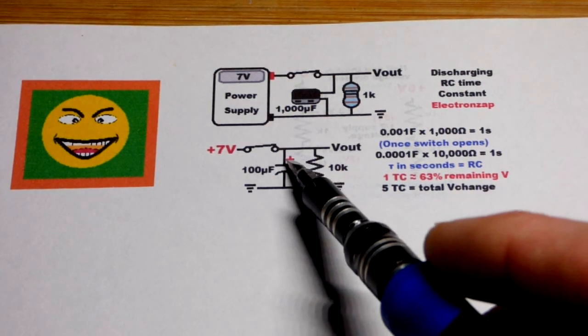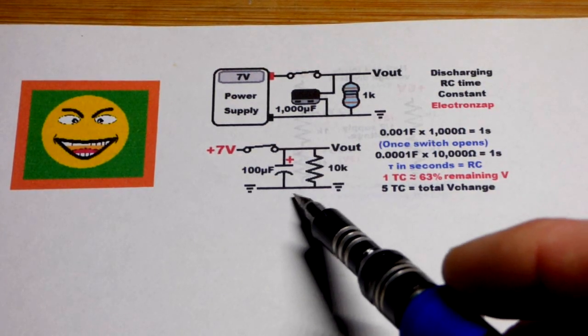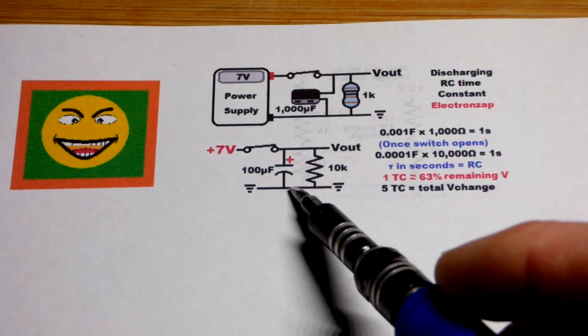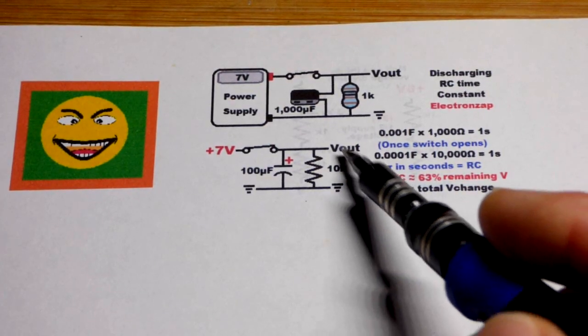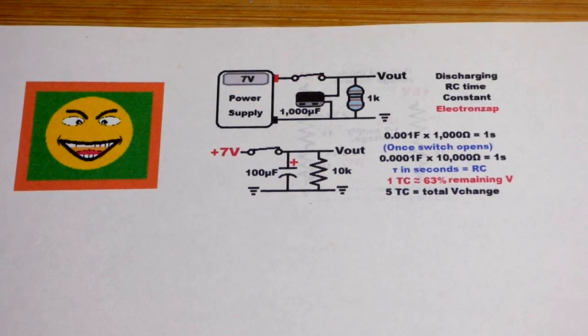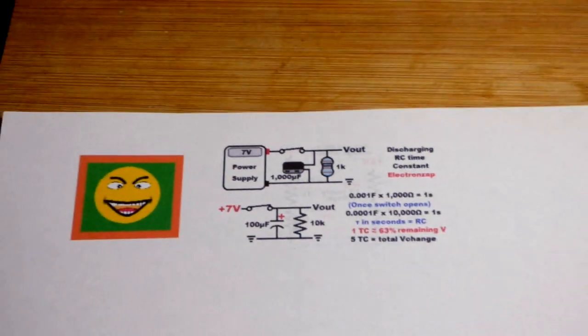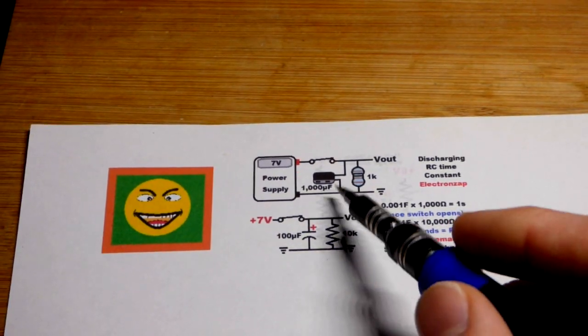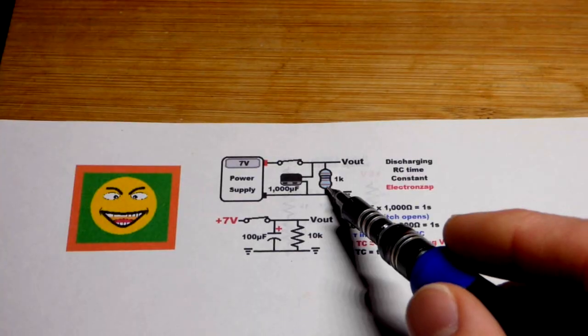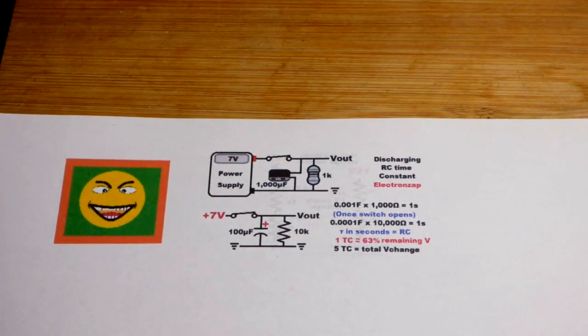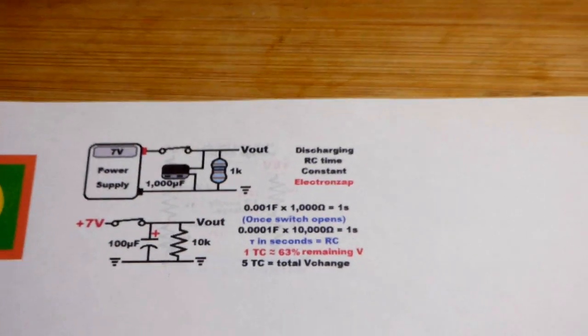You can charge the capacitor and then have it discharge through the resistor when you stop charging it, and you can take the time to do stuff. You can look at the voltage and whatnot. We'll zoom back and look at another version. 10 times the capacitance, 1/10 the resistance, gives you the same timing. Hopefully that makes sense. So we'll zoom in.